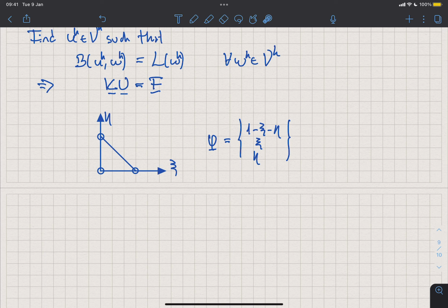The moment, of course, that we want to apply this to a real triangle, what's it going to look like? Well, I'm going to have some triangle in real space that looks something like this. And using this idea of an isoparametric formulation, we basically describe the geometry as the sum of shape functions phi that are functions of psi and eta, multiplied by the coordinates of the element, right?